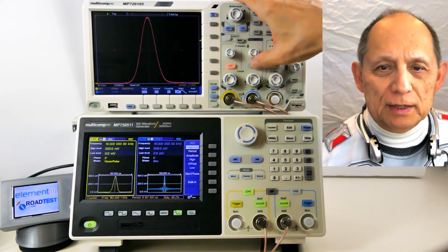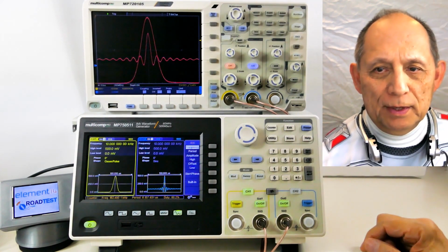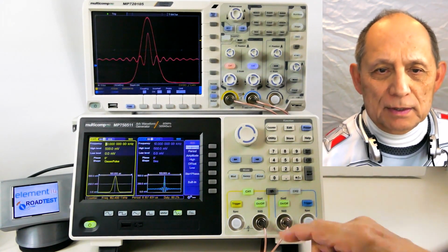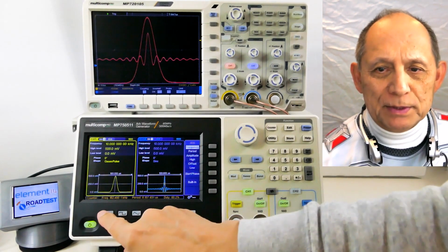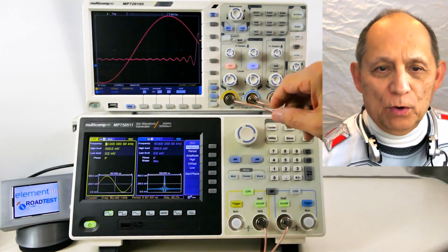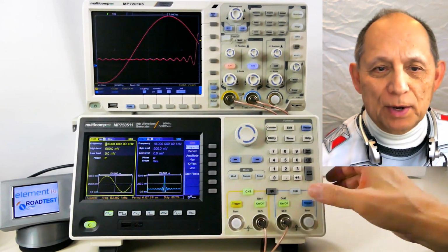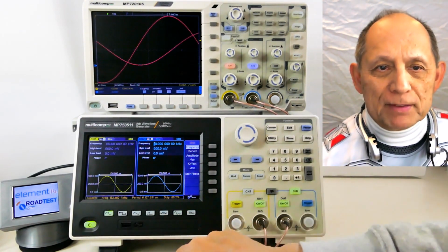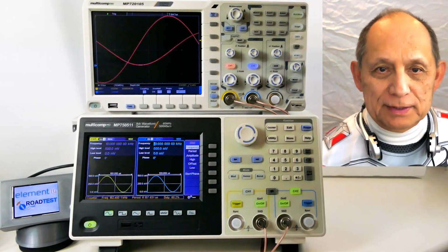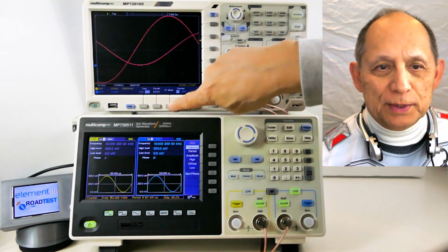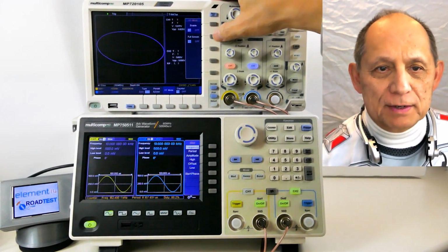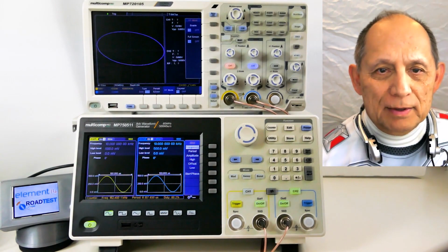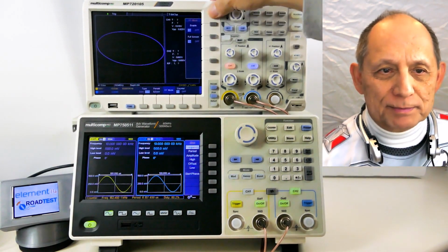I'm using a dual-channel Multicomp Pro oscilloscope to help show the signals. Although the waveform generator itself has its own view of the waveform on each channel, the scope will help demonstrate what the signals look like when overlapped or plotted in an XY mode. Of course, the generator can generate simple sine waves, and the scope shows what they look like as XY Lissajous figures when the frequency and phase are varied. I'm always fascinated by this phenomenon.